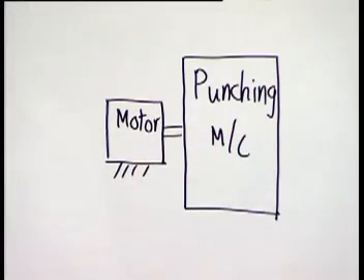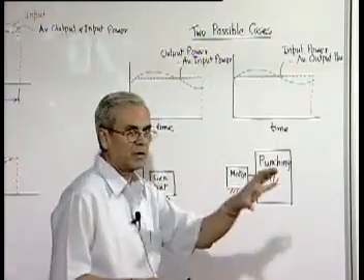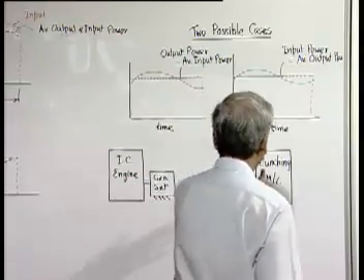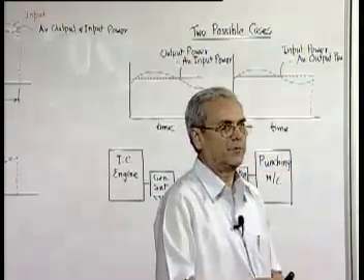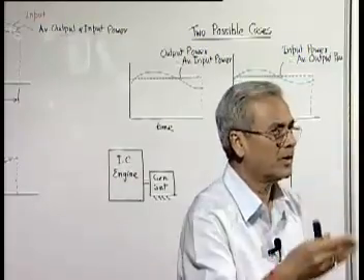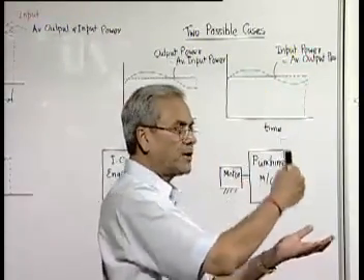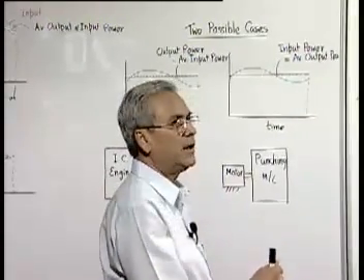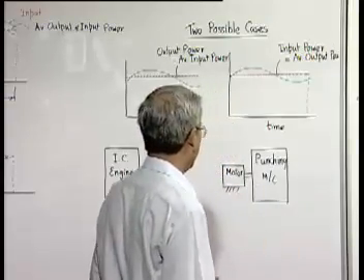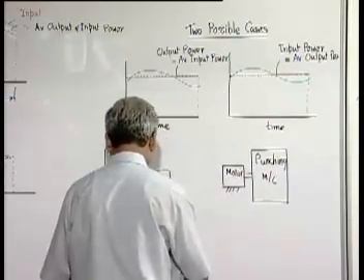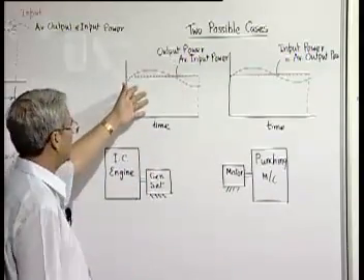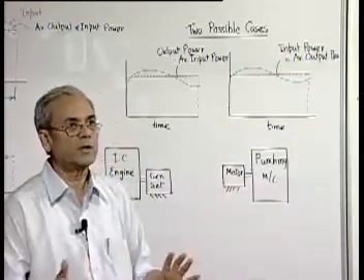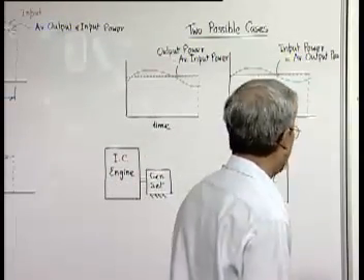So here what happens, the motor is producing a constant voltage and constant torque, so input is constant, but the load requirement is fluctuating. Most of the time there is no load except friction, then once the punch comes in contact with the plate or the sheet metal, immediately the load starts increasing. So here you will find that the situation is something like this, and in such cases the situation will be like this. In both the situations the speed will fluctuate.